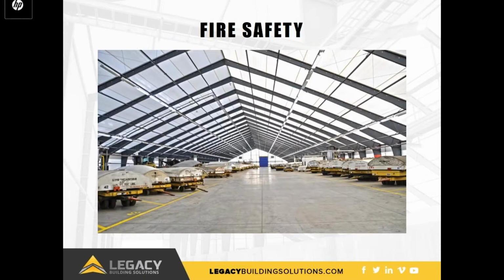For example, fabric structures are classified as Group 4 buildings by the National Fire Protection Association. In applications such as aviation, NFPA 409 states that Group 4 buildings with less than 12,000 square feet of fire area do not require a sprinkler. Larger buildings require significantly less aggressive sprinkler systems, potentially saving thousands of dollars during initial construction and over the lifespan of the building.